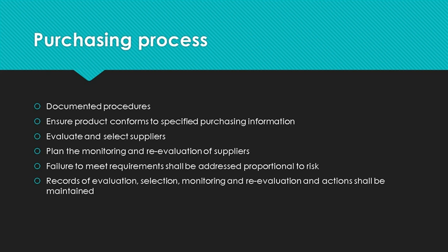The procedure must define how suppliers are evaluated and selected and be proportional to the risk. If your process is simply a requirement that the supplier is ISO certified, please make sure that their certifying body is accredited. Otherwise, the certificate is not worth the paper it's written on. Other methods are a self-survey and/or audit of the process or evaluation of multiple lots of product.